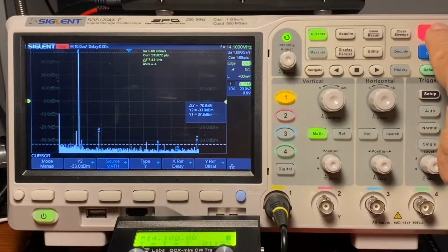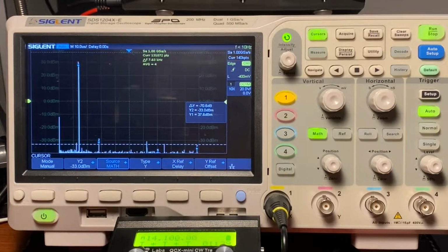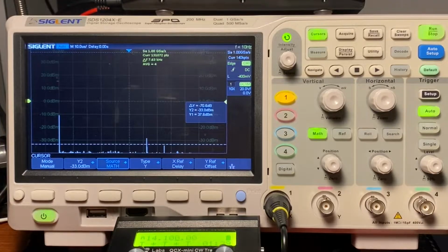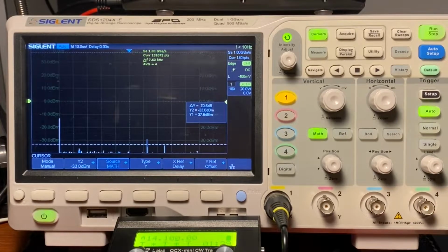Now, if I run back on with the transmitter off, as it is, we have one problem we have to account for, and that's that we still see some signals. The first one is that at the fundamental frequency, occasionally we'll see a signal popping up down in the noise, around 80 decibels below our reference level, or minus 40 dBm.